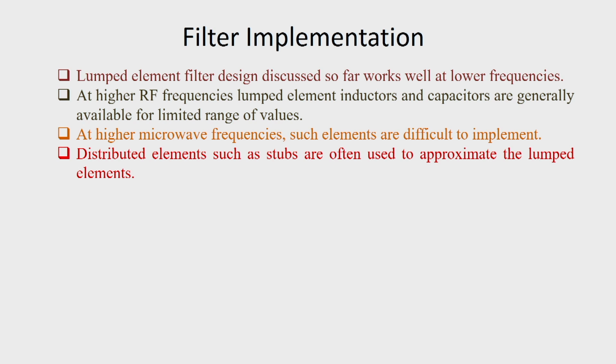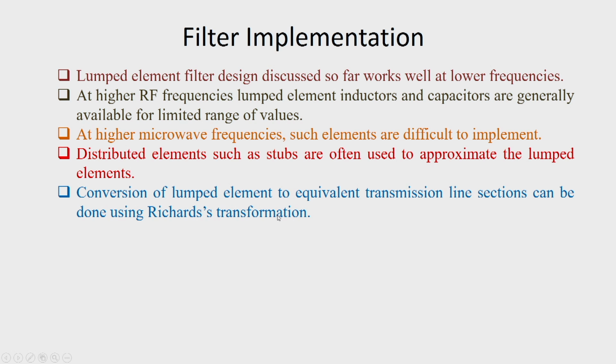So, we need to use distributed element such as stubs, which often used to approximate the lumped elements, and conversion of lumped element to equivalent transmission line sections can be done using Richards transformation.